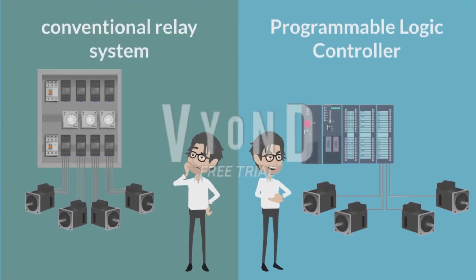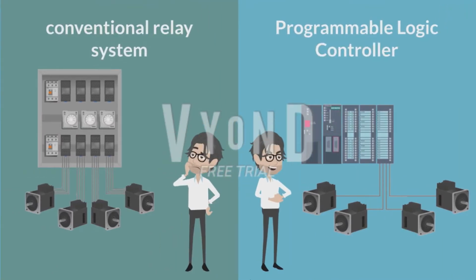Another great point the PLC has over a conventional relay network is the ease of troubleshooting. In a relay system, there will be more wires, relays, and other components that are not needed in a PLC. You can only imagine how much easier it is to troubleshoot the multiple output PLC system compared to the relay system with 4 times the amount of wires.